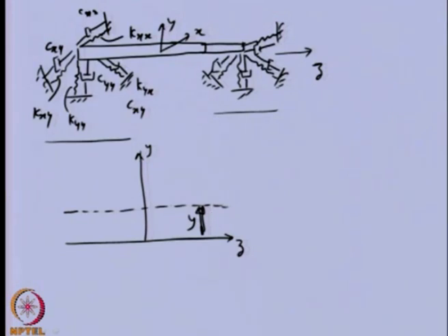Earlier we had both the radial and axial eccentricity of the rotor. So this is the axial eccentricity in the z direction, and because the rotor is rotating, we have a centrifugal force which is offset from the center of the shaft.